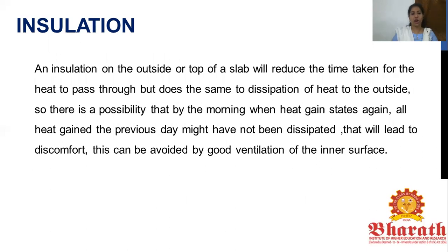So insulation on the outside or top of a slab will reduce the time taken for the heat to pass through, but does the same to the dissipation of the heat to the outside. So there is a possibility that by the morning, when the heat gain starts again, all the heat from the previous night might not have been dissipated. That will lead to discomfort, and this can be avoided by good ventilation of the inner surfaces.